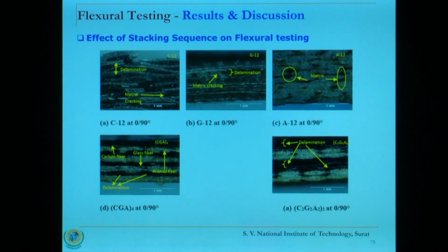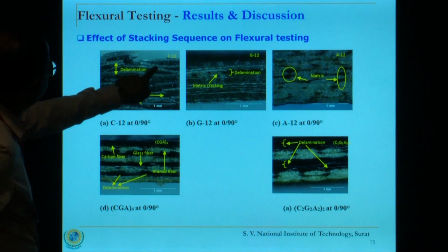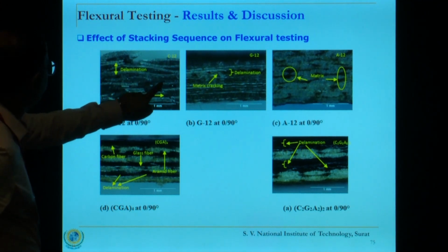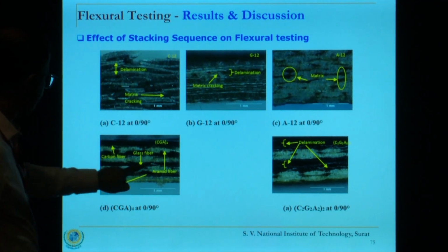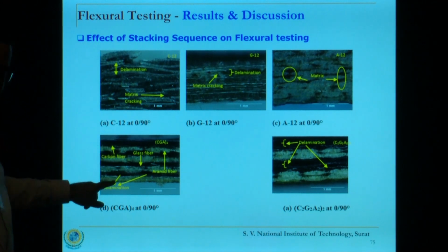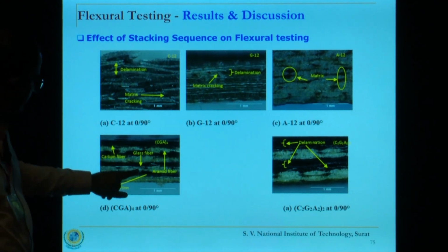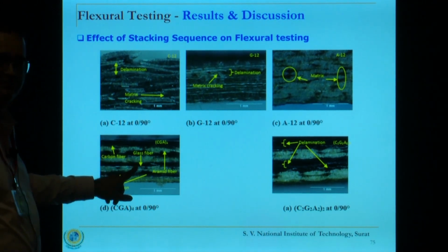The resin that remains between two specific layers of fabric gets separated, that is delamination. So, I observe two separate layers, right? I see these layers are separated, this layer is separated, and this one too. This delamination you observe more between the glass fibers.